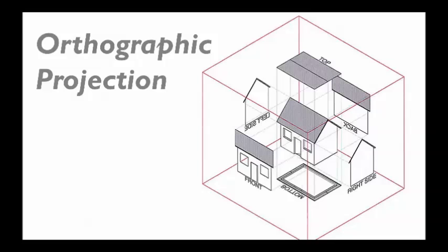And so the front and right and left and back sides that you see, it's as if we're taking actual points from the top roof portion, the walls, and literally pulling them apart, projecting them out perpendicular from the surface of the building, and that flattened view on the sides becomes the elevation drawings or the elevation views.